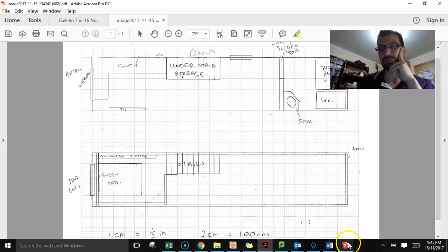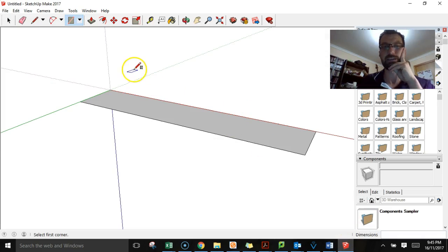What you do is use this thing called the offset tool. Offset tool here. What that does is it will create an exact copy, an exact distance away or inside of another one. I've got this. It works on these 2-dimensional faces, they're called.